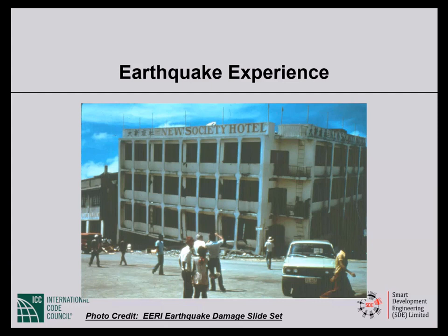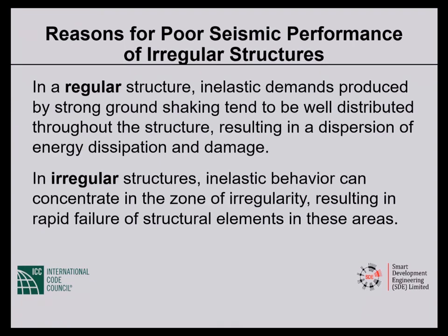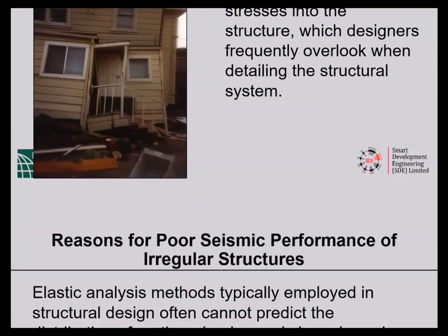And when the shear walls begin to yield, the loads transfer from those yielding elements to the frames. And you will not capture that out of elastic analysis. There is no way. So that's what we are trying to say on the slides that I was on.